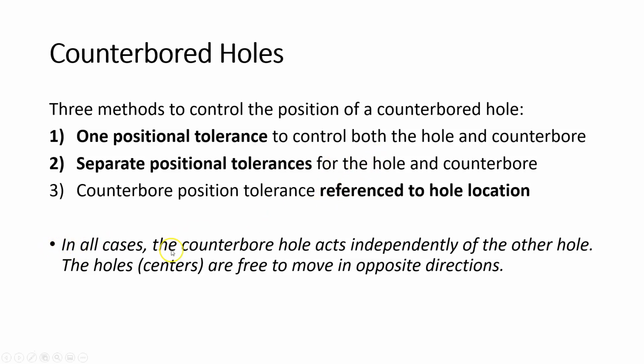In all cases, the counterbored hole acts independently of the main hole. The centers of the holes are free to move in opposite directions. So we're not talking about linking the counterbore hole with the through hole or the primary hole. In both cases, the holes can move independently.